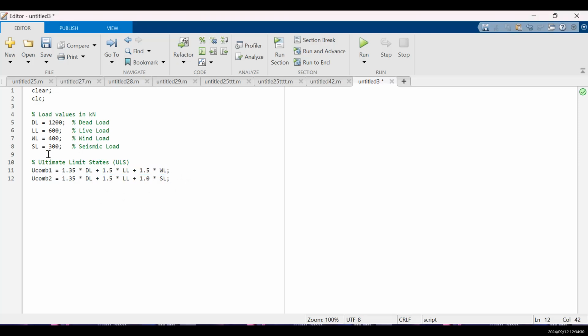All right. And for the second part, I'm gonna also consider the seismic loads. So I'm gonna combine the live load and the dead load. Those should be the main combination, right? And then here the factor is changing. For the seismic loads, we have 1.0, okay? You can see the difference between the wind load and seismic loads, right? For the wind loads, the safety factor is 1.5, but for the seismic load it is 1.0, right? So you have to make sure that this value here is constant, so don't change this value here, okay?